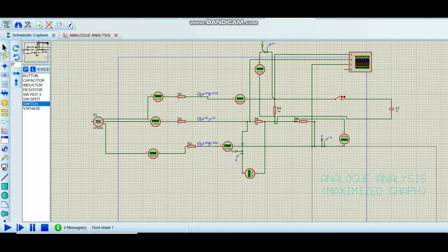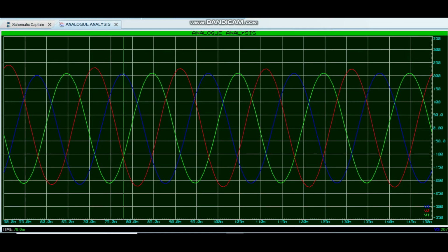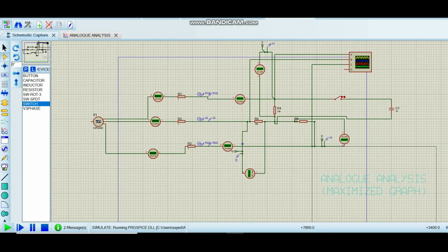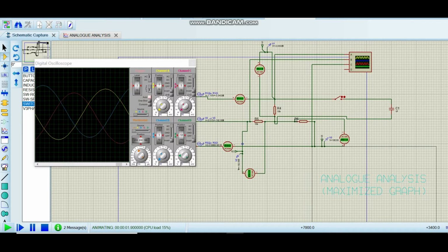Let us observe the voltages in normal conditions at 220 volts. As you can see, they are all at rated 220 volts. Now running the simulation, waiting for the transients to resolve, and then switching in the heavy reactive load to observe spikes. As you can see, the voltage has dipped. Removing it back to observe it return to its original position and switching it back in. The aim of the STATCOM is to control these spikes in real-time systems.